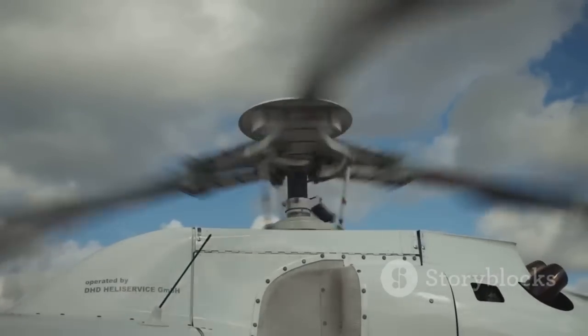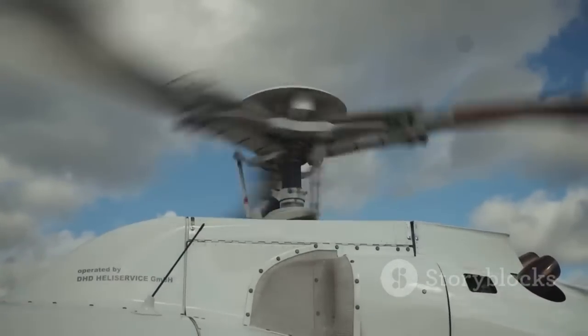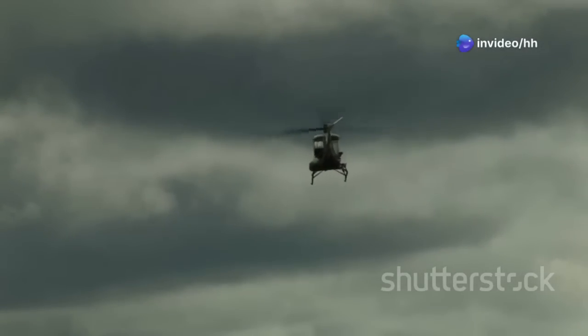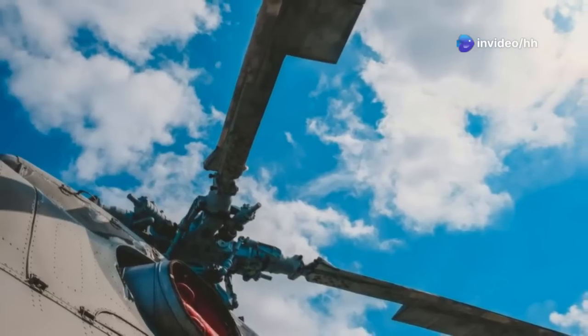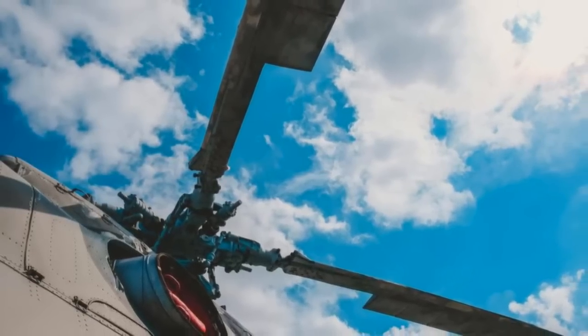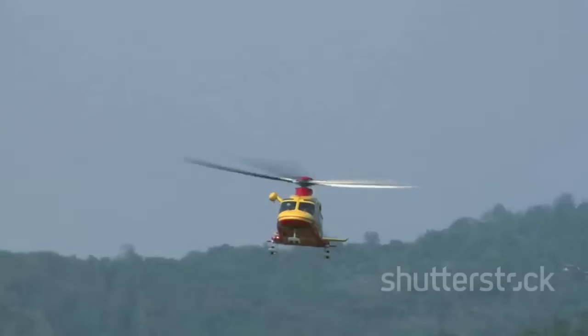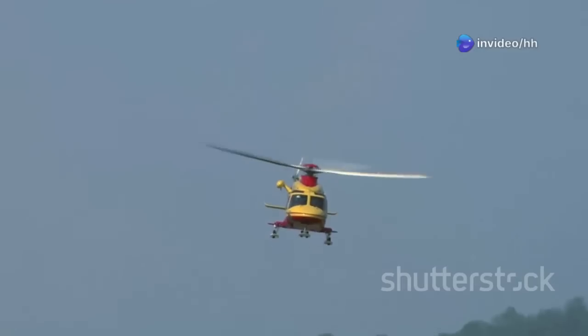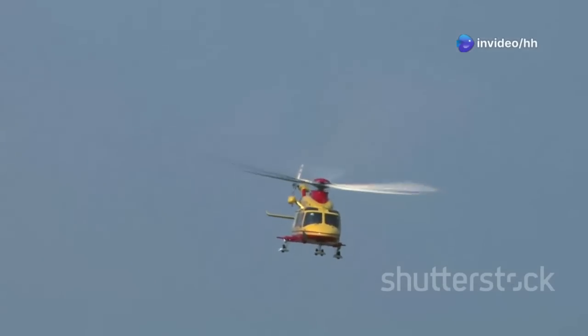Non-symmetrical airfoils. These airfoils are more common and are the workhorses of lift generation. They are designed to maximize efficiency and performance. They have a curved upper surface and a flatter lower surface. This design helps in creating a pressure difference that generates lift. This asymmetry is what makes them so effective at producing lift, making them ideal for a helicopter's main rotor blades.